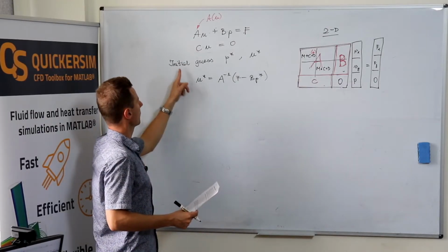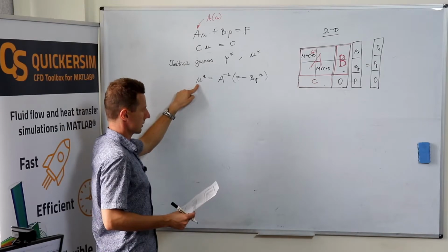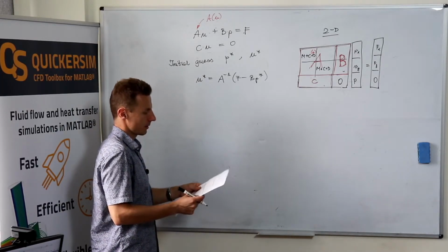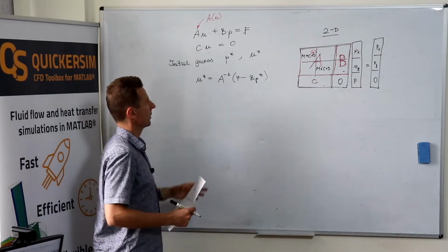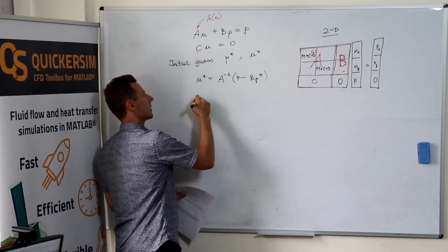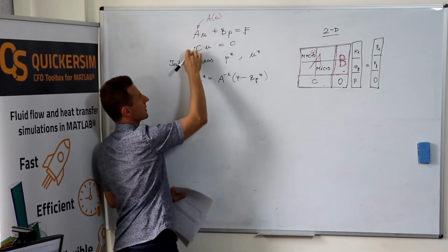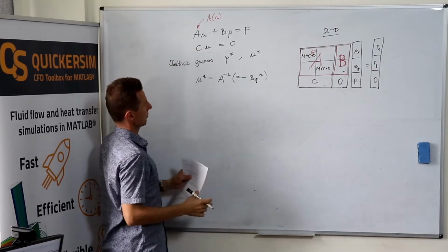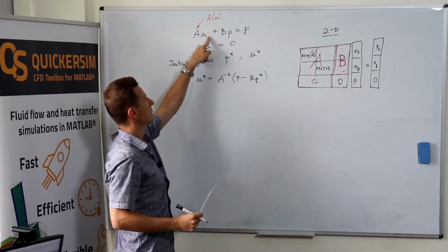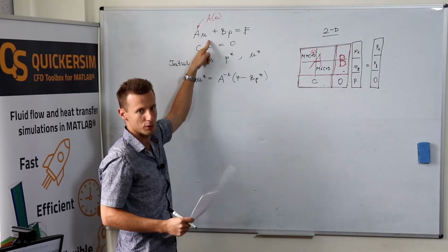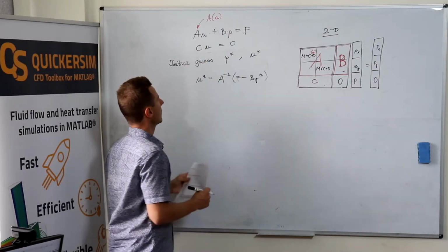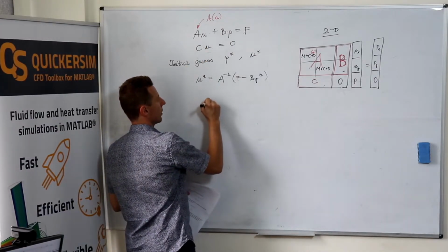And we've got the initial guess for the velocity field. What have we got then? We make the observation that this set of equations is not really written for some initial approximation. It's written for the physically correct velocity and the real physically correct pressure. So we make the following observation.